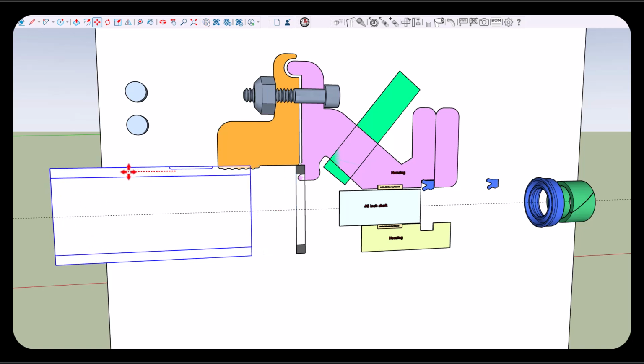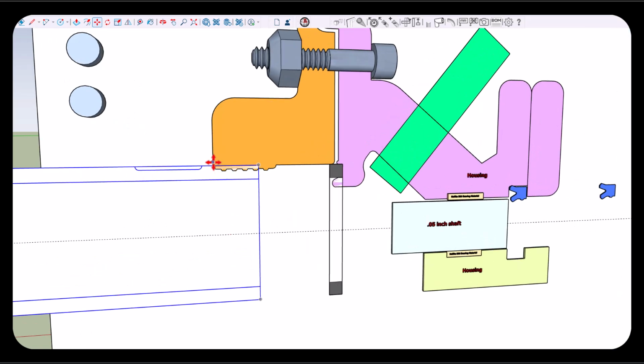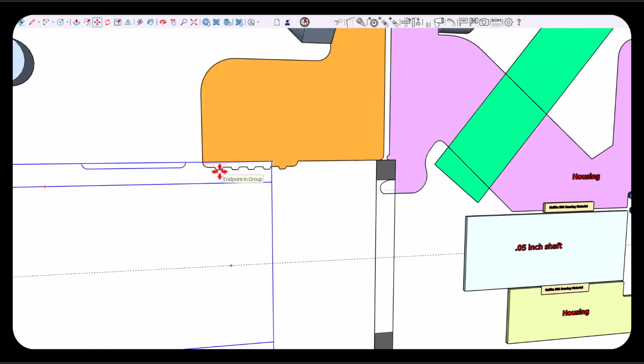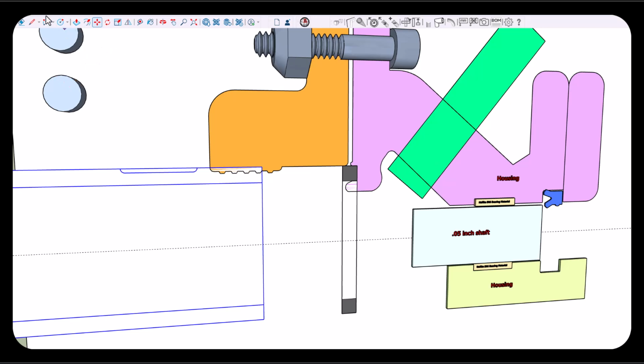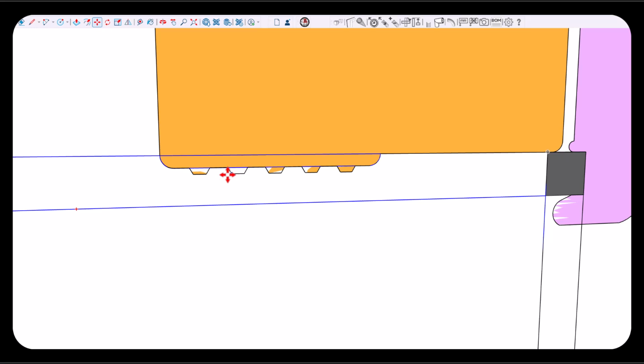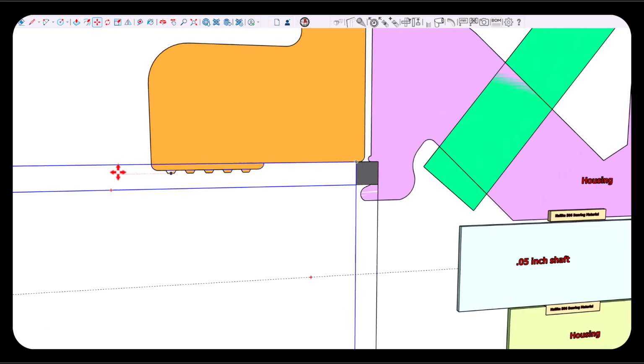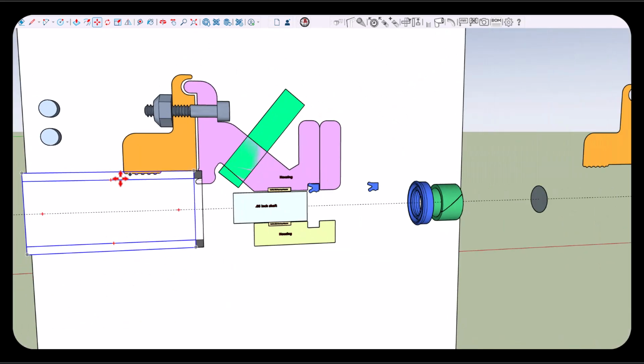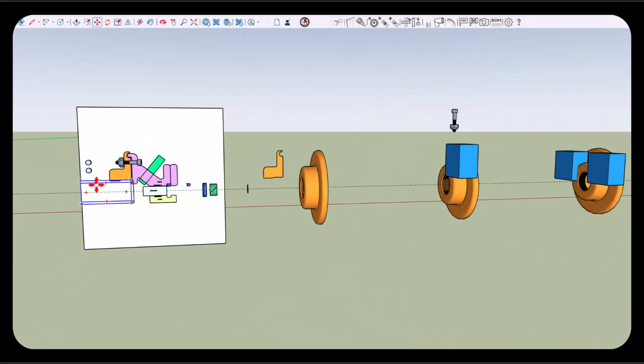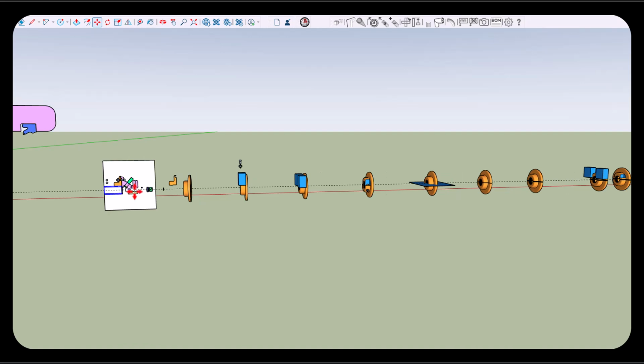There's that groove, and the curve of this groove matches the curve of this structure. And these little 1/32 inch teeth stick down into the Delrin. So the Delrin stops right here, and these teeth are pushing down into it, and that grabs a hold of it. And it is my hope that that will hold it strongly enough that it won't go anywhere.